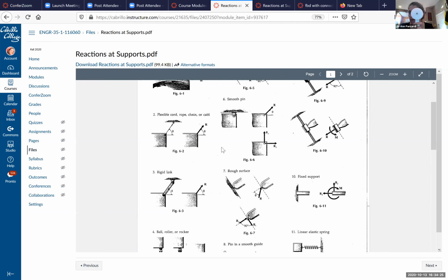Okay, how about Angel? What other kind of motion can this pulley and this rod have in relationship to each other that the pin might be preventing, since it's 2D? There could be a translational motion in the x. Yeah. And there could be a translational motion in the y. So there are 3 different types of motion that a 2-dimensional connection can withstand. One is a translational motion, let's say a force in the x, a translational motion in the y, and a rotational motion about the z.